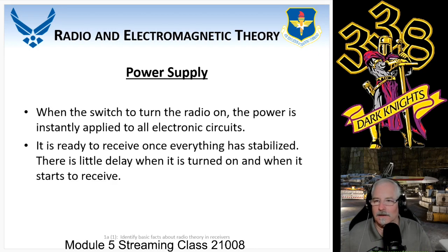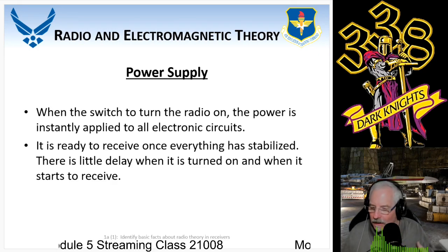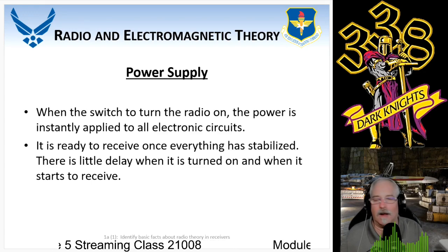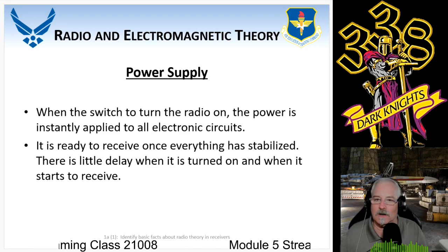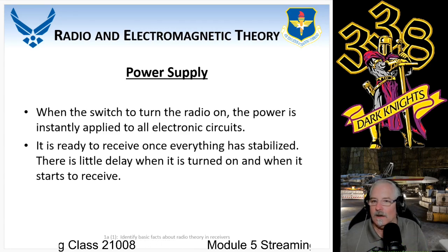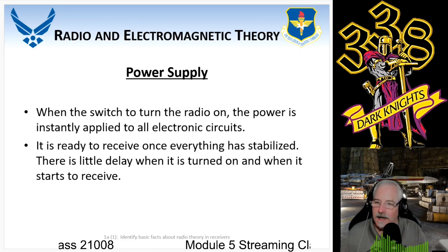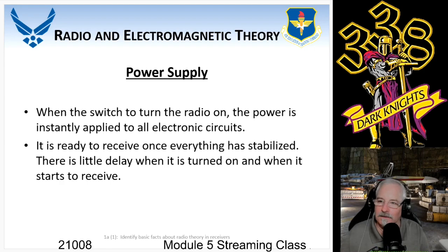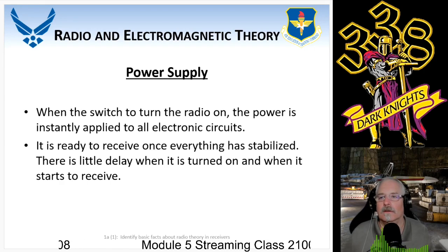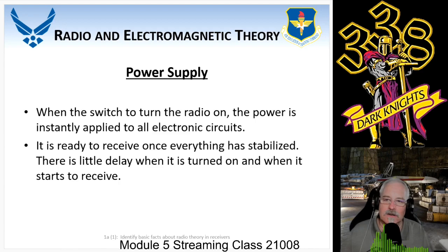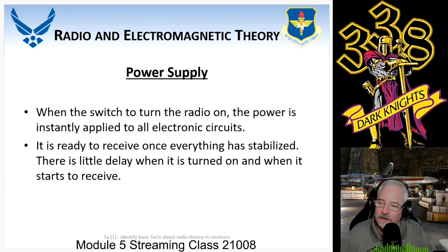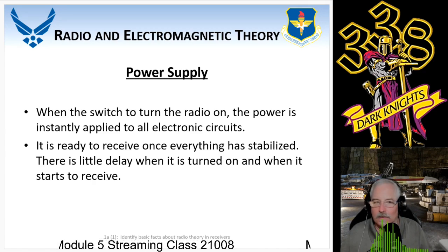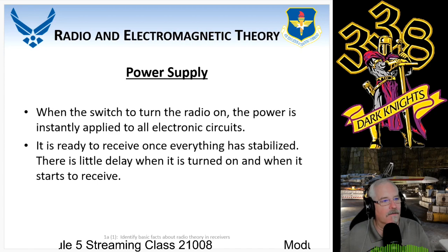When you turn it on, the phase comparator is looking at what the VCO and the reference is doing, and if the VCO is not on target, it's going to send an error voltage. Well, what happens when you turn it on? It's not instantaneous. It's got to build up to it. So it can take up to a couple seconds. I've seen radios that tell you that it takes a half an hour for that oscillator to warm up. It's acceptable. It just depends on what you have as far as the equipment that's out there.